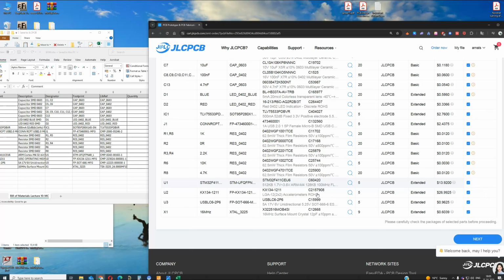So let's see if the orientation is correct. We can see it from here, see this is wrong. So this is pin 1 and we have the indicator for pin 1 here. So rotate, and that's correct now. Unfortunately, it's always like that. You have to check your main components. For the passives, it doesn't matter.